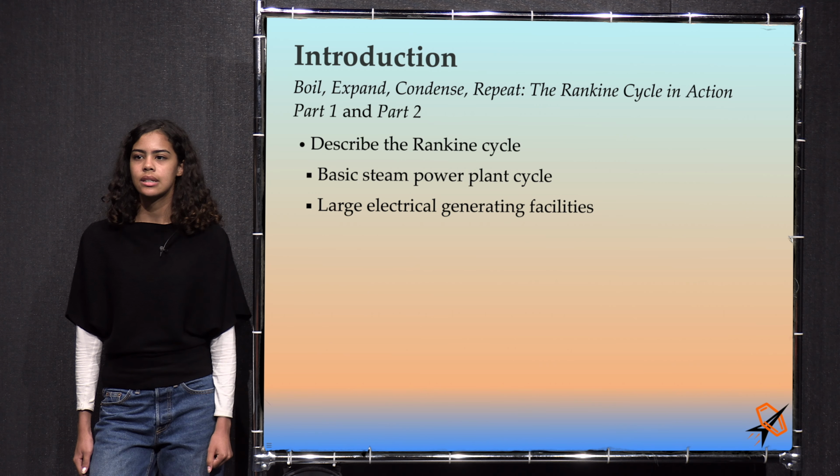So what are the engineering problems with the steam Carnot cycle? Well, one problem is that the turbine operates largely in the two-phase region. Why is that a problem? Well, tiny water droplets at high temperatures tend to erode metal turbine blades very badly, and the lower the quality of the steam, the worse the erosion is. You don't want to have to be replacing your turbine blades every few months. It's very expensive. Another engineering problem is, as we mentioned before, it is an awful lot of work to compress a vapor or a gas, and compressing a two-phase mixture is just really challenging.